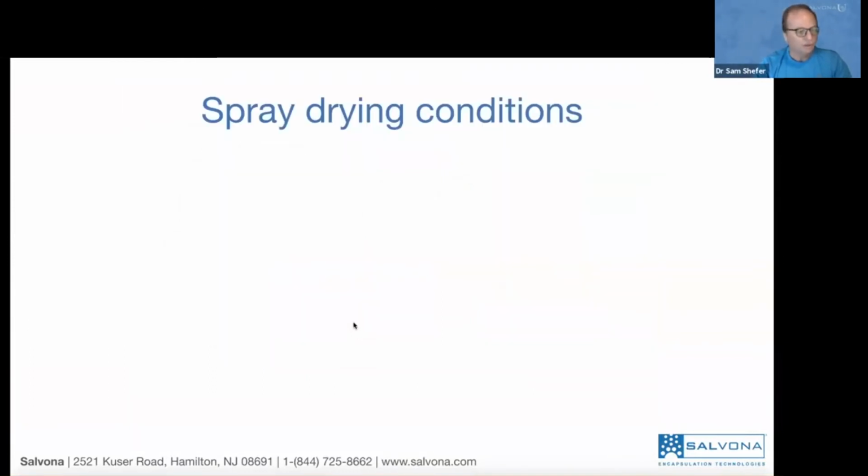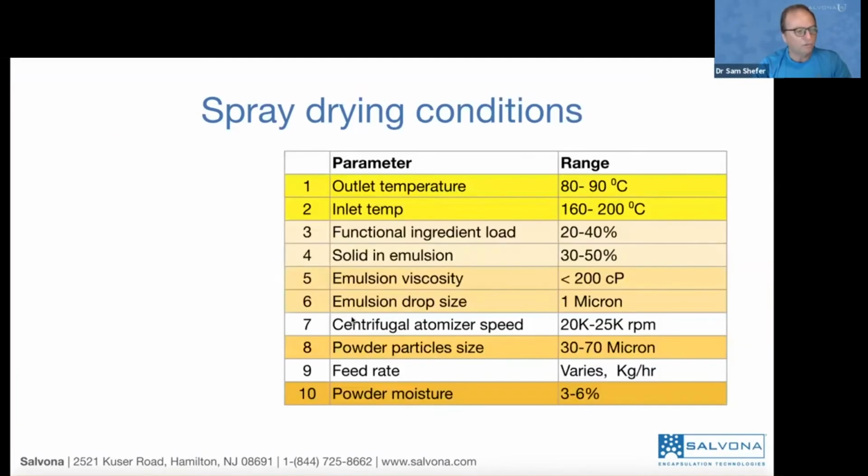So what are the conditions? I don't know if you will remember it. Maybe Jack has to remember it because he's going to control this. It's important to control the outlet temperature, the temperature at which we collect, and the inlet, the temperature that goes in. Look at this: the evaporation of water is 100. We are using a higher temperature than the evaporation. We force high heat, but we lose the heat because the heat is drying out the water.